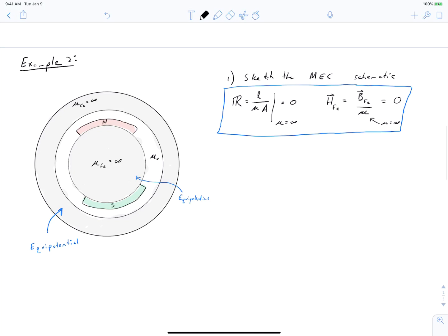Let's start on the rotor. We'll put a node right here, which is our rotor. Moving from the rotor, our circuit has a line going toward the stator. We have a permanent magnet, and that permanent magnet has a reluctance associated with it and an MMF source. We'll draw this in the Thevenin equivalent form. So here's the MMF, or the equivalent current linkage of our permanent magnet. We've got the reluctance of the permanent magnet drawn here, and next we have a reluctance associated with the air gap between the magnet and the stator.